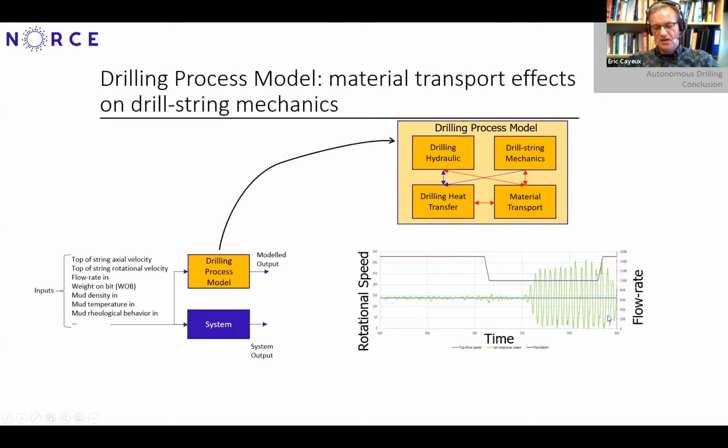And you may think, okay, this is something which is simulated, but this is actually something that we have observed with high frequency measurements in actual drilling operations. Each time there was downlinking to the BHA, and there was a change of flow rates, there was a generation of extremely heavy stick-slips. And when the downlinking was finished, this stick-slip was disappearing.